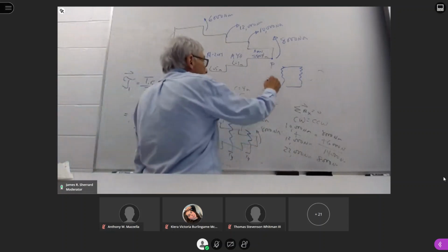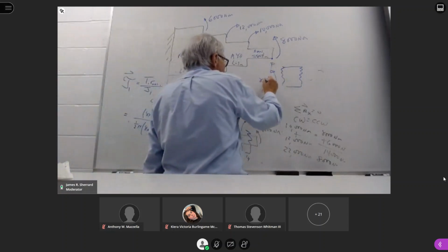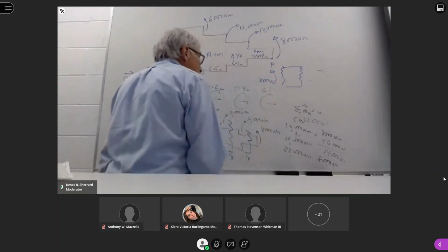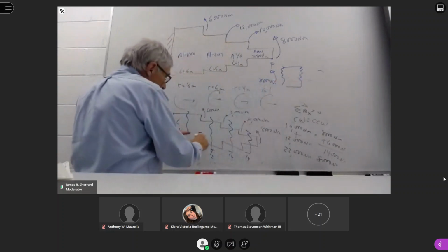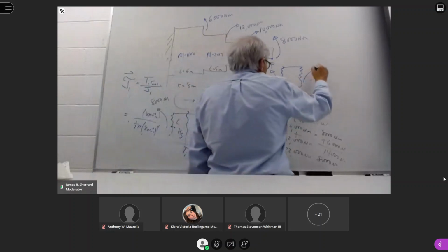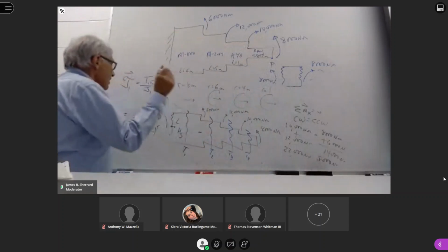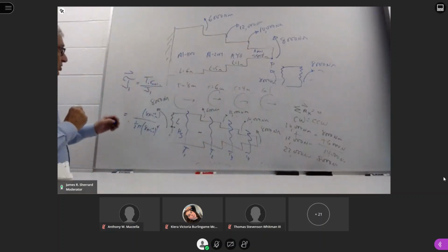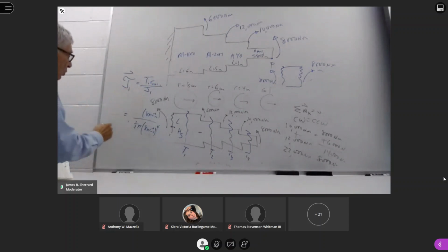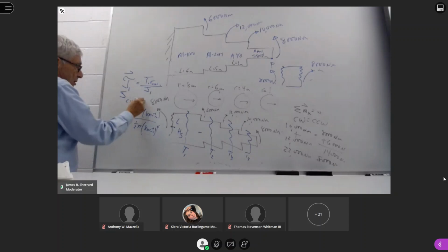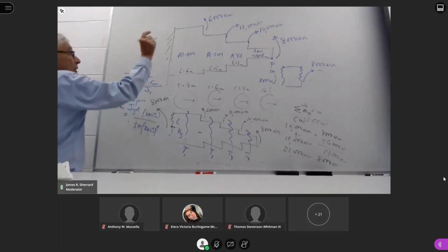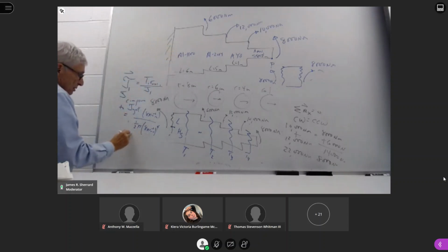We have the 8,000 acting here, and one attachment point where the left hand joins the right hand. So that's the value I'm going to use in that equation. I'm going to do this math, and whatever this value comes out to be, I'm going to compare it to the yield value for aluminum 1100, which we know is 55 megapascals.